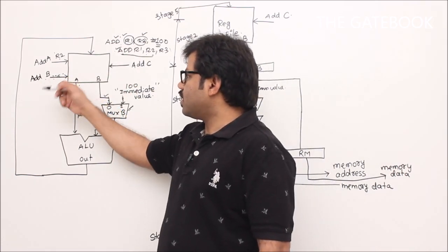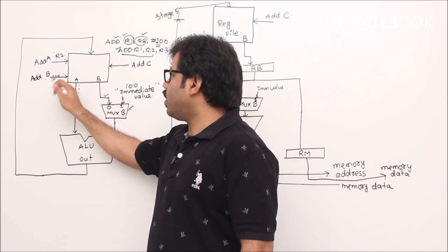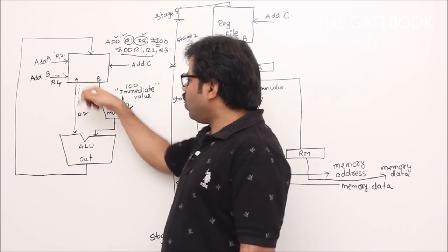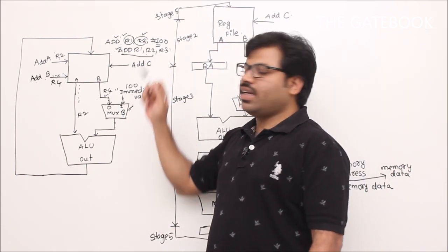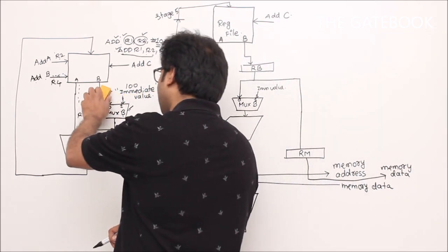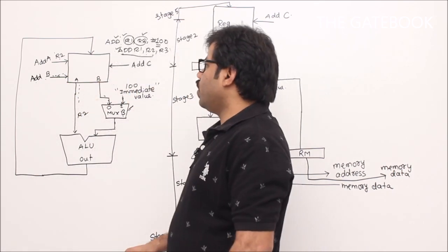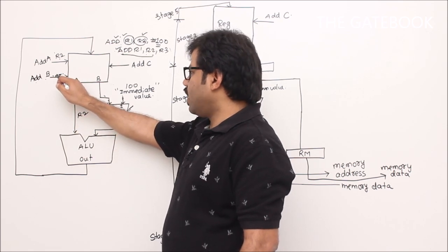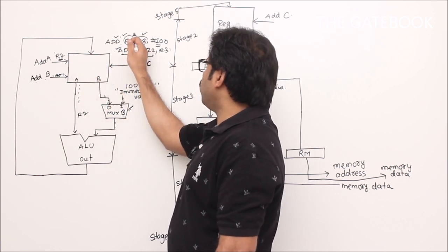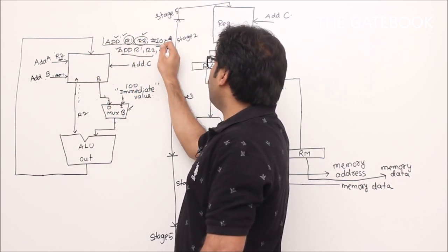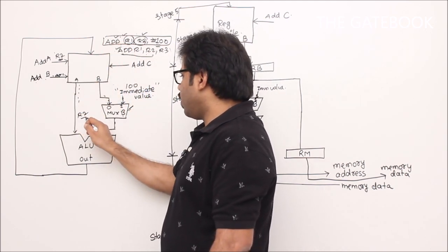So that means, for example, in the previous instruction this add B, address B, was connected to something, R4, then that R4 register will be enabled here. Sir, then you get wrong, right? R4 was not our intention. Yes, not a problem. Because if you execute things properly, we will not be specifying any valid address here, but only giving a valid address here, R2. Slowly R2 comes. I am showing you how to execute add R1 R2 hash 100 using the circuit. So R2 slowly comes here, perfect.